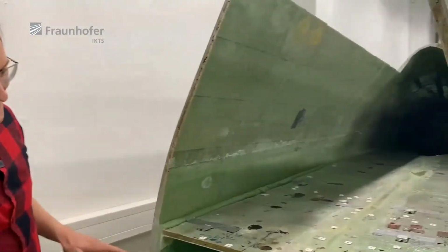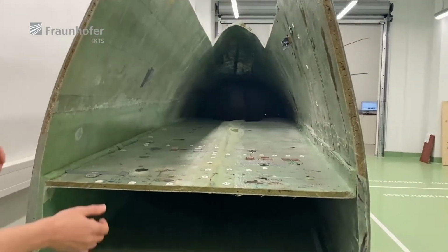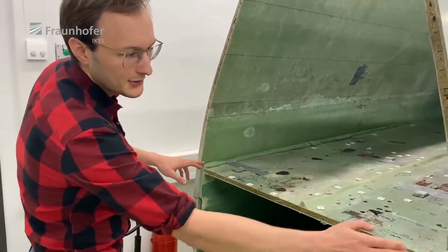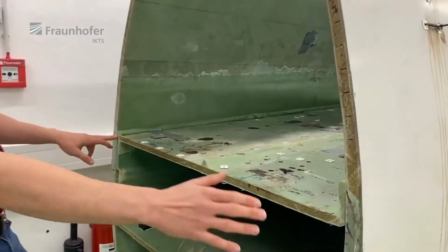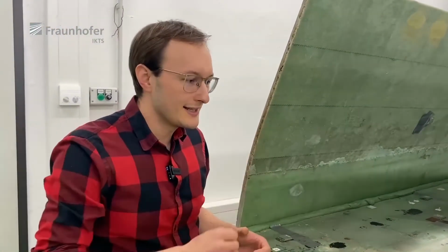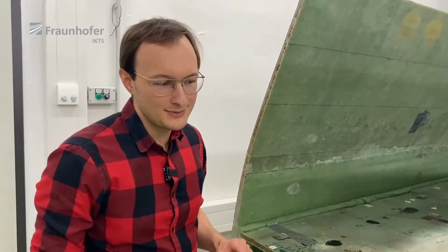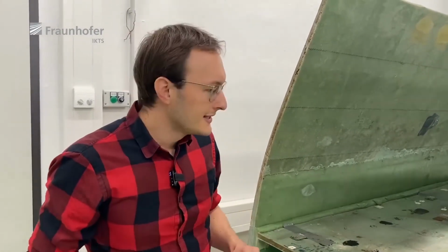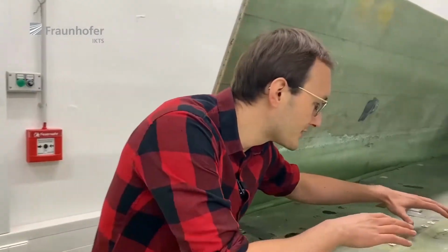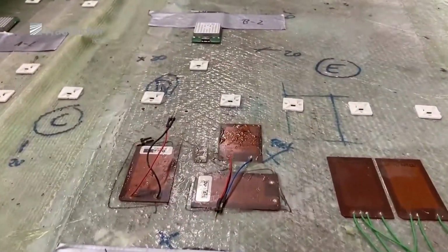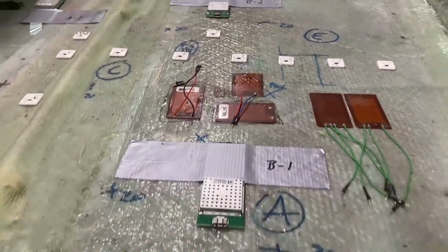You can see how the rotor blade is made. You have glass fiber on the outside and on the inside, and here you have some joints where the parts are glued together. So of course, if the wind comes, there's a lot of stress going against the whole structure. And sometimes tiny micro cracks can happen. Actually, they happen all the time. And we assemble our sensors on the inside at different positions to listen very closely to when and where those cracks happen.